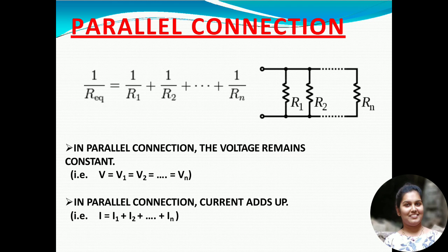These 2 basic connections show us that the value of resistance will increase when resistors are connected in series, and the value of resistance will decrease when you connect the resistors in parallel combination. So though the value of each resistor may not change, the connection makes the total resistance increase or decrease. It is not that any connection is okay.